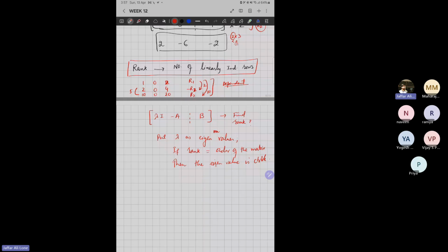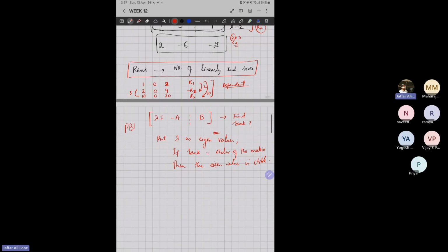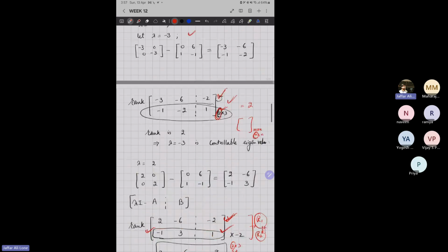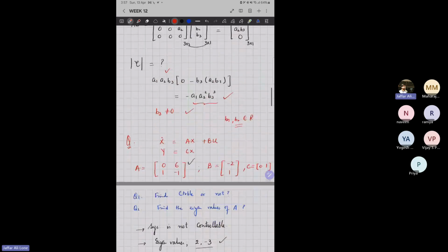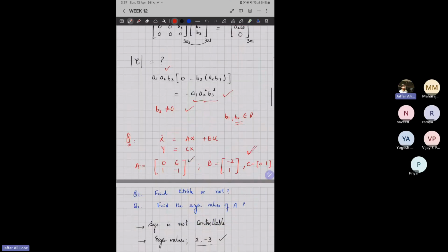Okay. So in these questions where you're asked to find the uncontrollable or controllable eigenvalue, you just follow this PBH test. This is one way, right? Or if you have a single input, single output system like this, with only one input and one output, the state space can be converted into a transfer function, right? You can easily convert it by using C into (sI minus A) inverse into B.